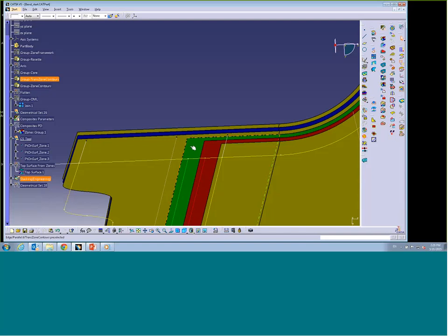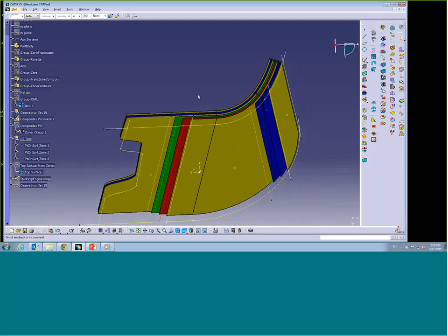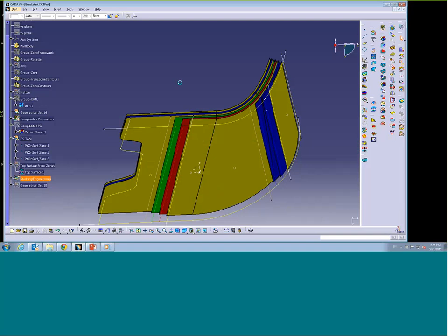So if I wanted to create plies non-uniformly spaced, like some kind of custom transition with different offsets, I would have to use a different method. We're not covering it today, but the method would be to use full plies and ETBS. ETBS stands for edge to be staggered. With this approach, it will also create a file in which I can actually customize the offset from one ply to another. Okay, but let's say I'm happy with the plies I have.